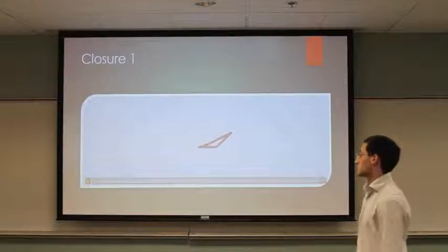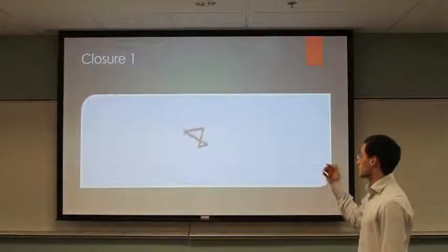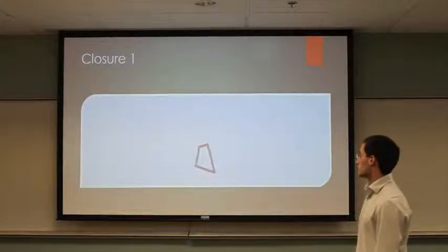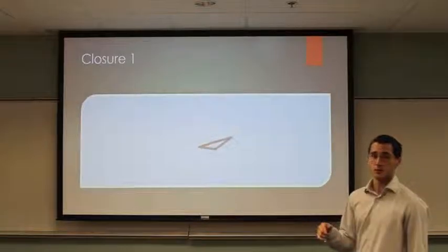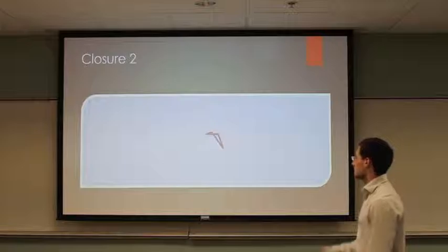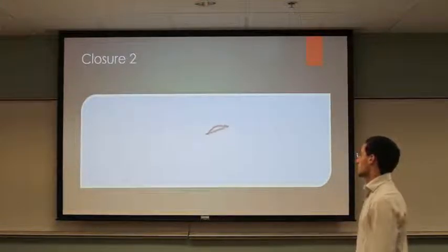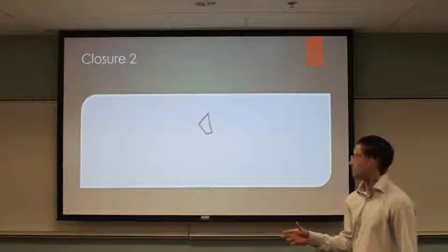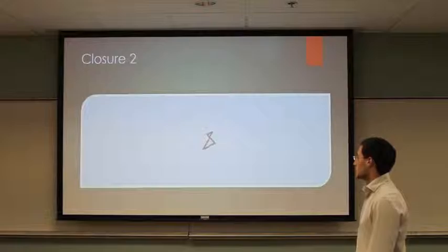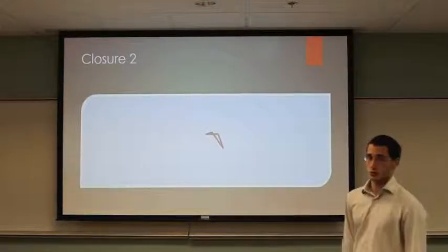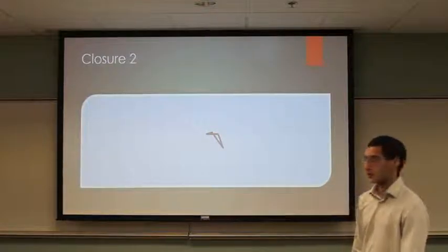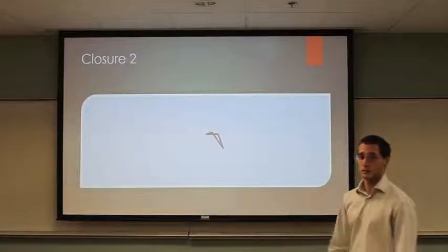For our first solution, the system will behave as such. The input angle is for the link R2, and it will rotate at a constant rate for 360 degrees, and the link lengths will follow. The second solution, shown on the next slide, is in this animation here. As you can see, it follows a similar circular path, and link 2 again rotates 360 degrees. The biggest difference between closure 1 and closure 2, or solution 1 and 2, is that they're inversions of each other, but their behavior and their circular path are pretty much the same.